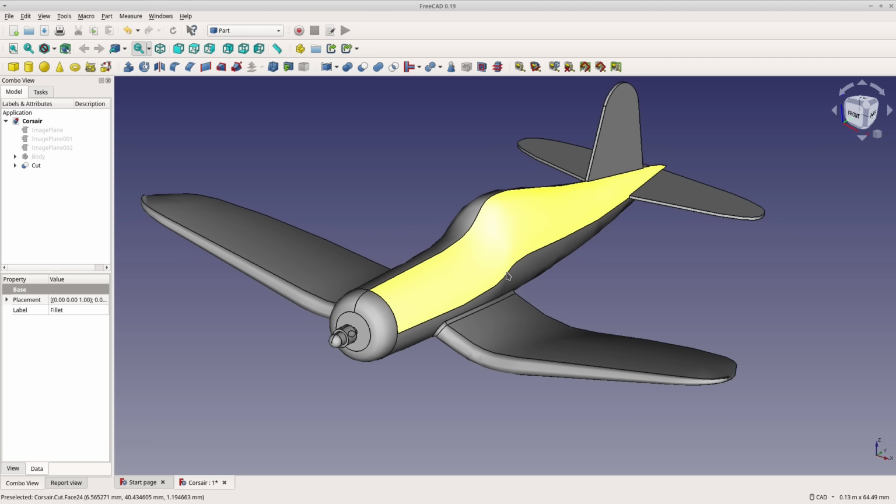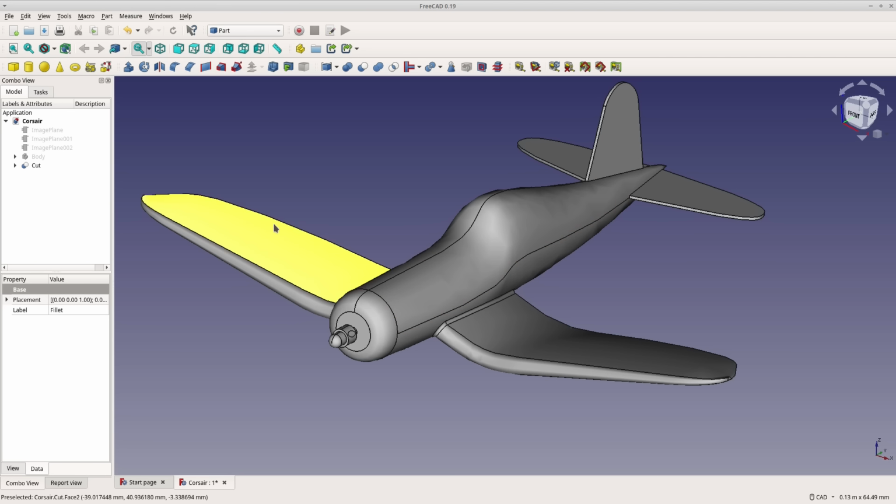So now that this is all set for analyzing, let's talk about what kind of mesh we're going to need to have. If you recall in the previous flow example, we did an internal flow study and we modeled the internal part of a pipe, meshed that, and flowed it. So whatever we model for the meshing, we want to have a solid there. Now that's not always true. In SolidWorks and other platforms you have a different take, where in SolidWorks you need a sealed volume to flow, but in FreeCAD we want to have a solid where we're going to flow.